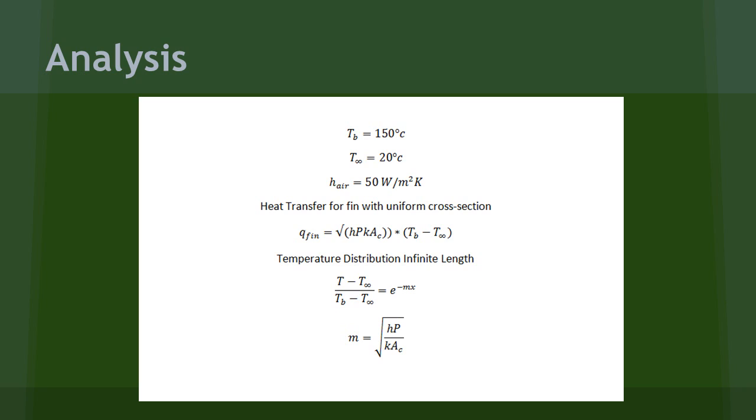The results from Ansys were compared to standard textbook equations, using a temperature at the base of 150 degrees Celsius and a bulk temperature of 20 degrees Celsius. These equations were used to compare the overall heat transfer of the fins and the temperature difference along the fin.